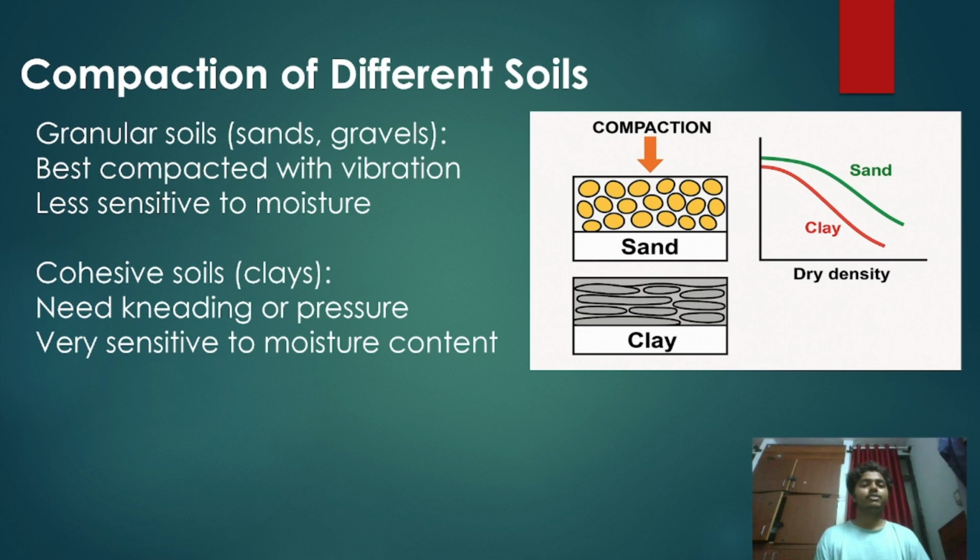For granular soil, such as sand and gravels, it is best compacted with vibration and is less sensitive to moisture. Cohesive soil or clay needs kneading or pressure and is very sensitive to moisture content. This is the point for this part.